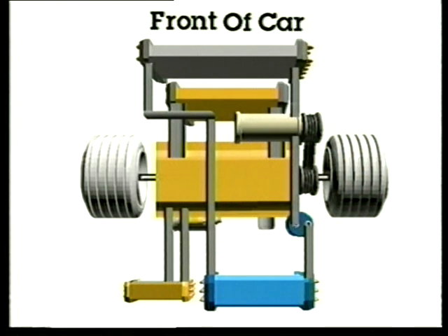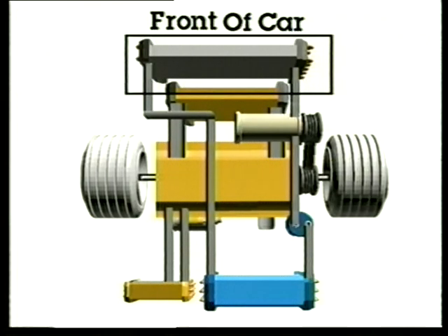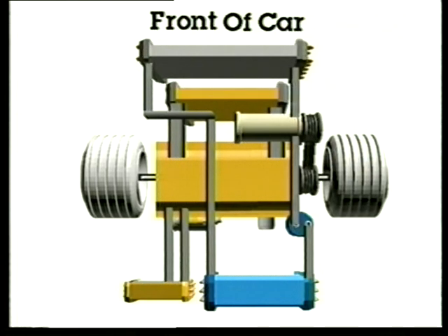The basic parts of an automotive air conditioning system include a condenser which mounts at the front of the car to remove heat, a compressor that bolts to the engine and pumps refrigerant to other parts of the system, an accumulator that mounts before the compressor to collect moisture and liquid refrigerant, an evaporator mounted on the firewall for cooling the passenger compartment, a heater core also on the firewall for warming the passenger compartment.